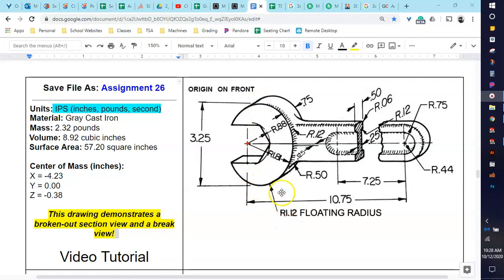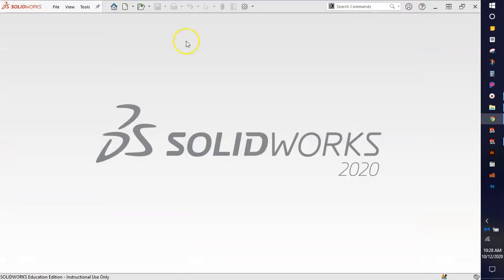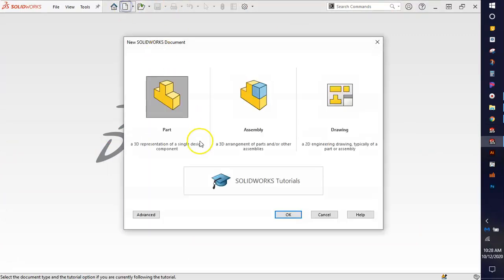So the curve that this is pointing to is actually this little piece here and up here because it's the same thing. And it does not have a defined center point. It's not like it's locked onto the origin or on a corner somewhere. It's floating and it will become fully defined once you do all these other measurements. So let's pull this to the side, and in SOLIDWORKS we're going to start a new part.